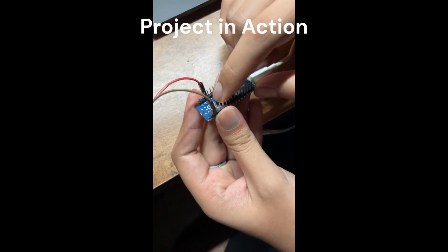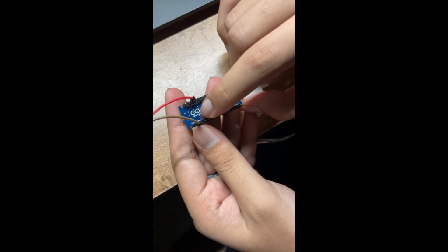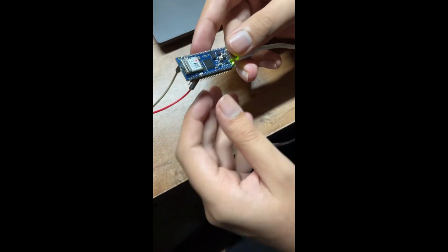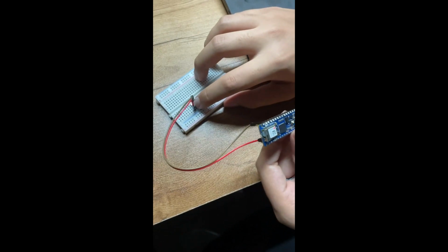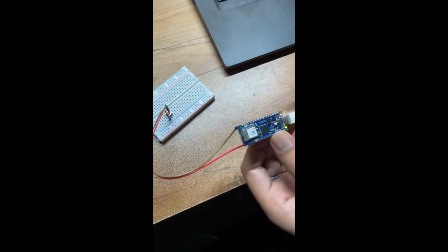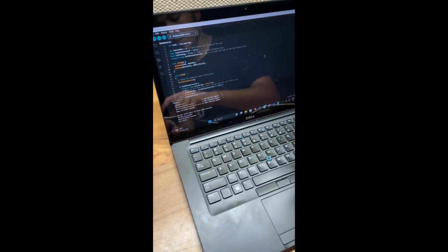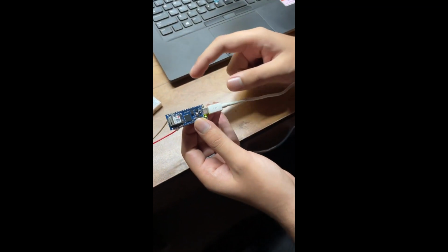As you can see, I have used RST, which is reset, and GND, which is the ground pin. Whenever I push this button, it is connected to RST, and after pressing it, the circuit restarts, and the name will be displayed in Morse code from the beginning itself.